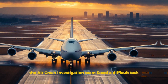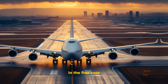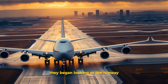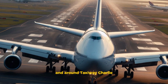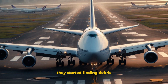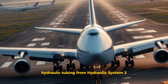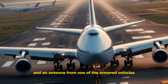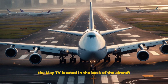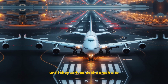The air crash investigation team faced a difficult task, determining why this occurred. In the first case, they went outside and began searching for clues. They began looking at the runway and around taxiway Charlie, approximately where the aircraft would have rotated. They started finding debris. They discovered some pieces of aircraft skin, hydraulic tubing from hydraulic system 2, and an antenna from one of the armored vehicles, the MATV, located in the back of the aircraft. Then as they continued down the runway, they discovered more debris until they arrived at the crash site.